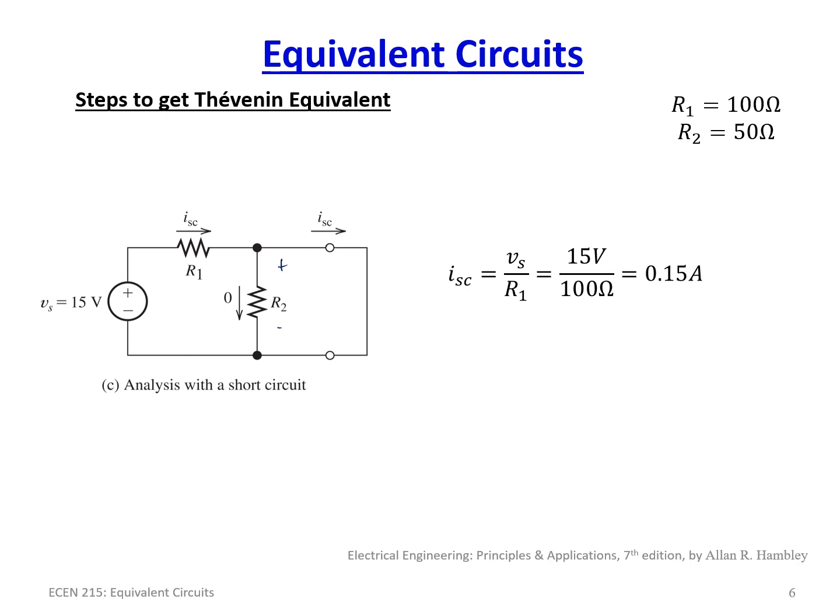So now that we know this, we can back out what RT is, and we get RT by using VT, which we had a moment ago, which was 5 volts, over the short circuit current, which happens to be 150 milliamps, and we end up with 33.3 ohms. Notice the change here. This isn't VS, this is VT.